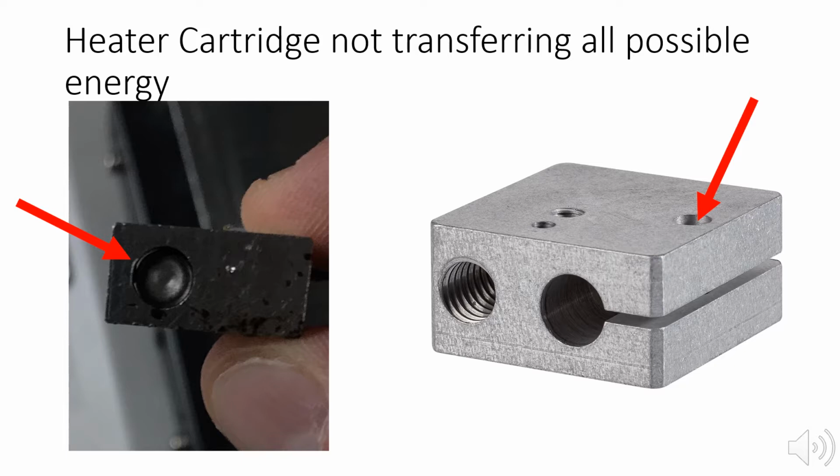Recognizing that significantly more heat will be transferred through direct contact than when there is an air gap between, we will multiply each measured power input by 5/8 and see if that gets closer to the experimental data. On a side note, after some research, it seems that the heat block shown on the right is more common, which has a screw that tightens the heat block around the cartridge.